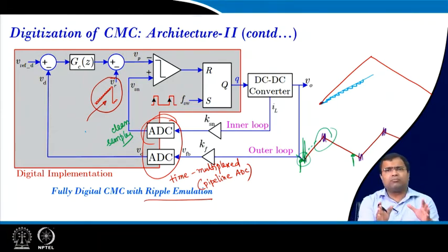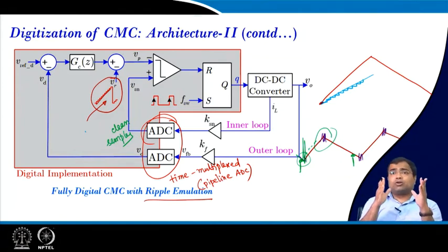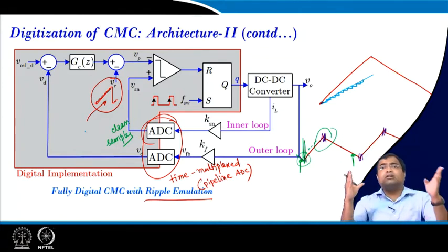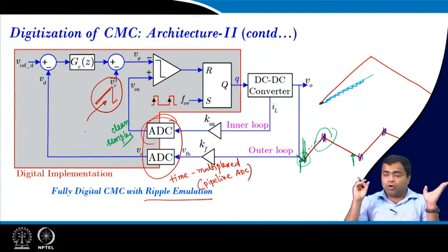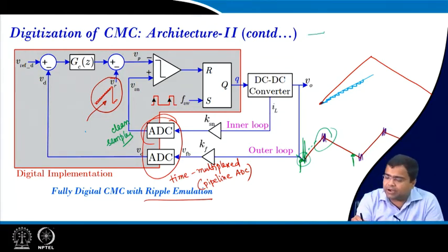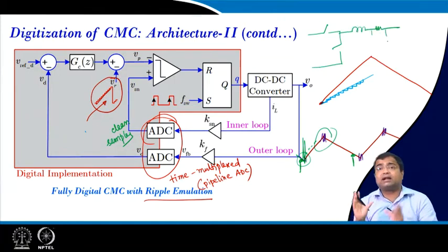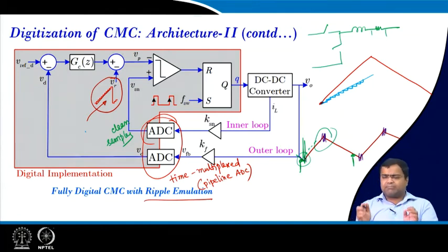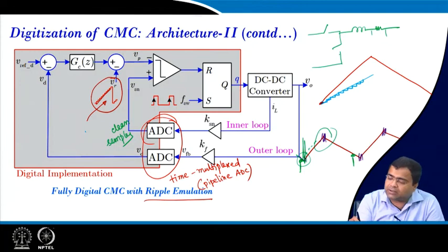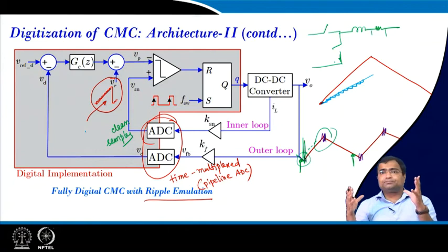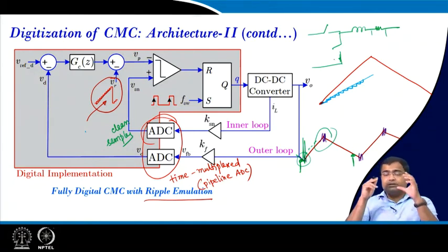And this is easy for a buck converter, but suppose you are talking about a converter where both sides of the inductor have a switch node. Or suppose we take a buck converter and place a current sense resistance across the inductor, then you will not have such an issue, or maybe very little. But suppose you are talking about a current sense resistance or maybe the RDS of the switch. When you talk about the RDS of the switch, this resistance is kept in the switching path.